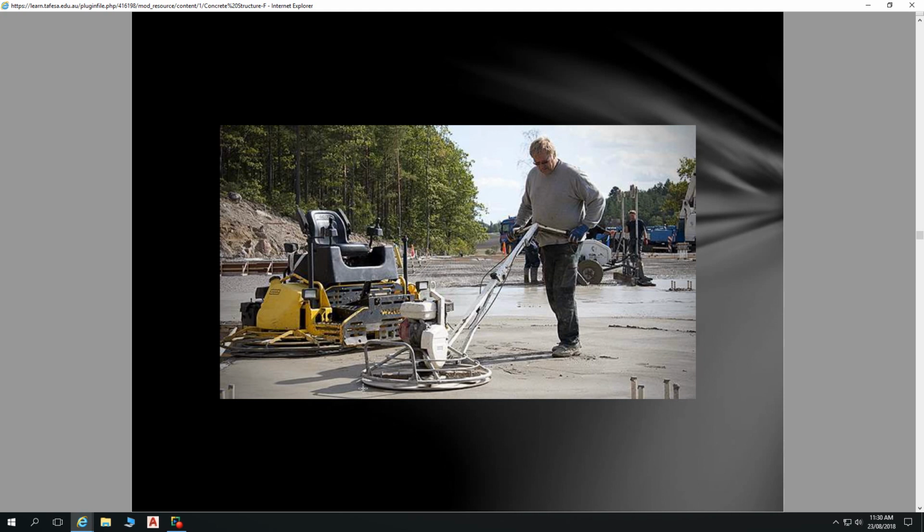Anti-slip. Yeah, anti-slip. So footpaths. You'll probably see footpaths that are laid down, then they'll get a stiff bristle broom and broom over the top, and then just do the edges really nicely. So they'll smooth off the edges, get those looking good, but then the whole centre section is all rough to give you grip. Now that can be done on footpaths, stairs, driveways, and so on.